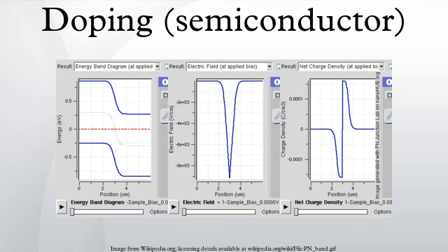Intrinsic carrier concentration varies between materials and is dependent on temperature. Silicon's ni, for example, is roughly 1.08 × 10^10 cm^-3 at 300 Kelvin. In general, an increase in doping concentration affords an increase in conductivity due to the higher concentration of carriers available for conduction. Degenerate semiconductors have conductivity levels comparable to metals and are often used in modern integrated circuits as a replacement for metal. Often superscript plus and minus symbols are used to denote relative doping concentration in semiconductors. For example, n+ denotes an n-type semiconductor with a high, often degenerate, doping concentration. Similarly, p− would indicate a very lightly doped p-type material.